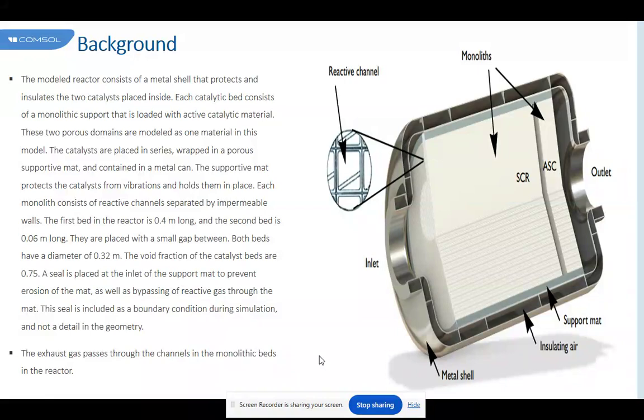This improved trade-off between back pressure and conversion efficiency shows the potential for monolith shape optimization by using heterogeneous cell densities. The most notorious and direct effect of using a heterogeneous cell density was a largely uneven fluid distribution. The fluid strongly prefers passing through the section with the lowest back pressure regardless of its placement, core or ring, or periphery of the substrate.